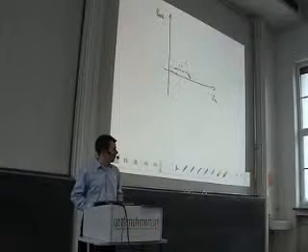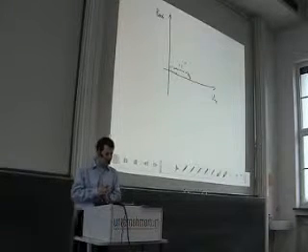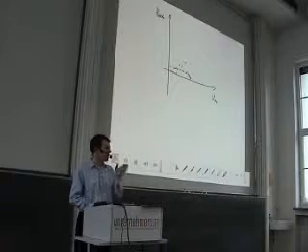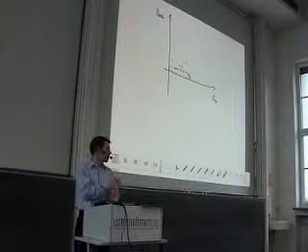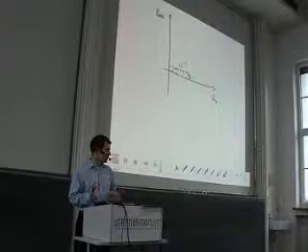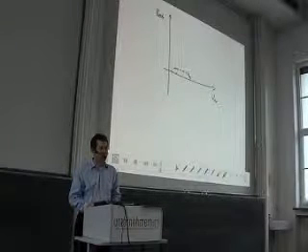And so on and so on. But you do not see the steps here. So what people usually do is to measure each point not only a single time, but measure each input voltage, let's say 100 times, and then do somehow an averaging. And if you do this averaging, then you end up with your step function.